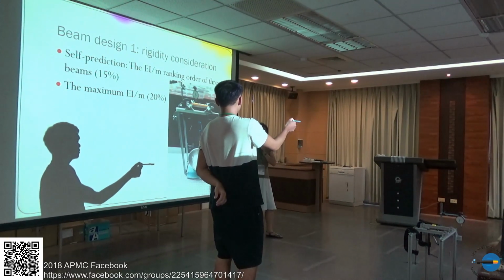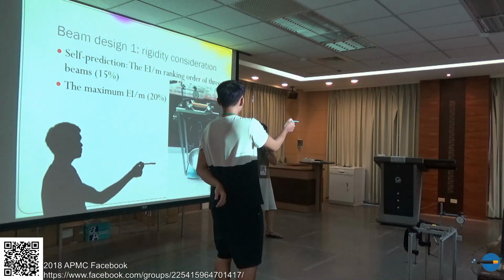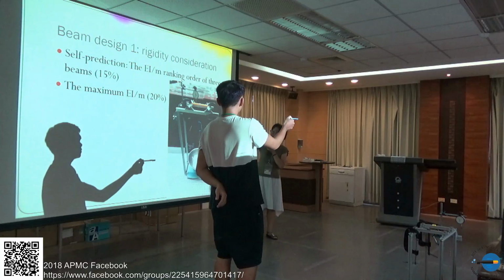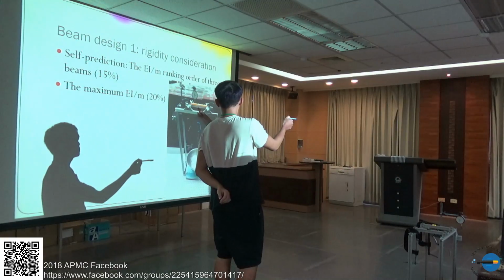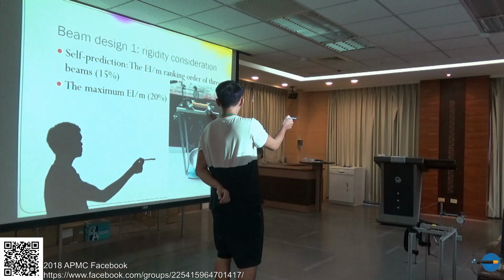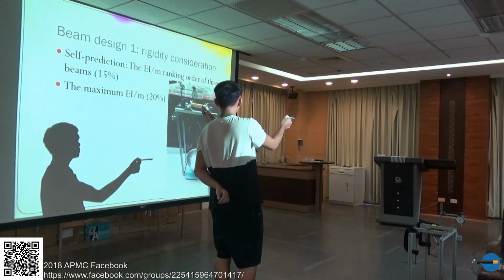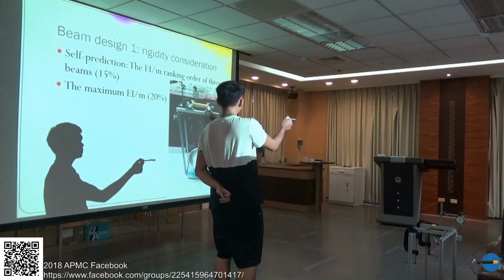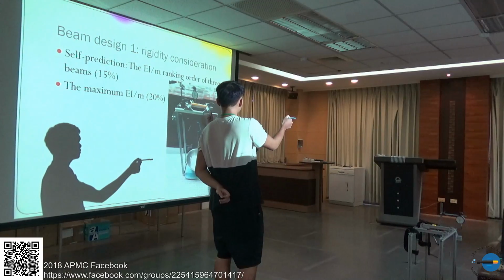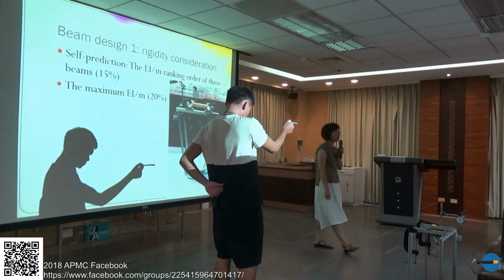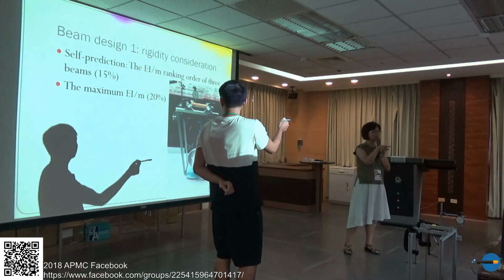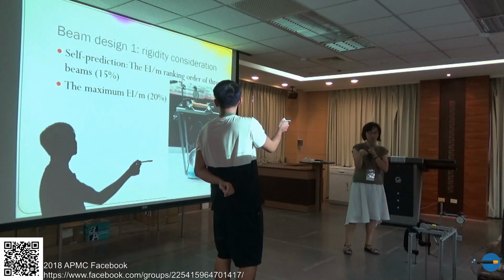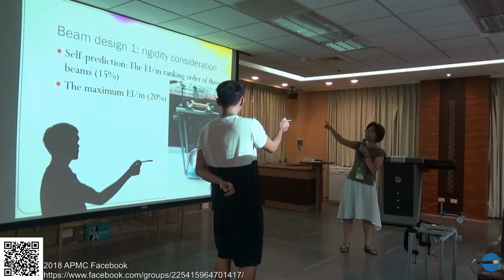That weight will be about 1.4 something kilogram. It's a lightweight. We will apply it at the center of this beam, and we will measure the displacement at the quarter length part. We will measure the displacement at this position. Based on that, we will calculate EI. You can find the equation in the rule. So we will derive or calculate EI.